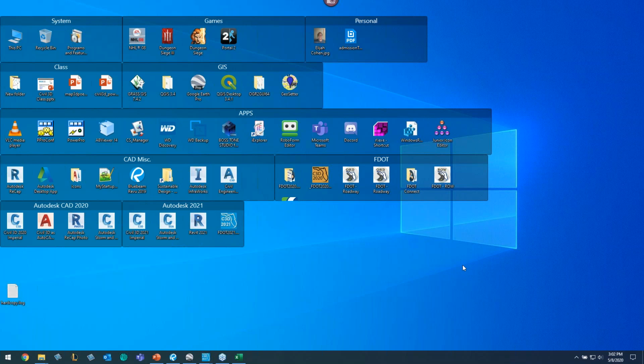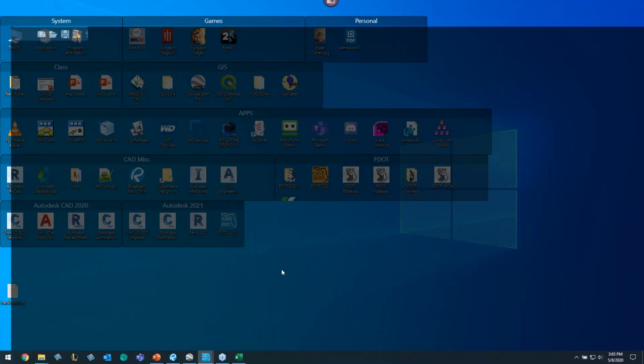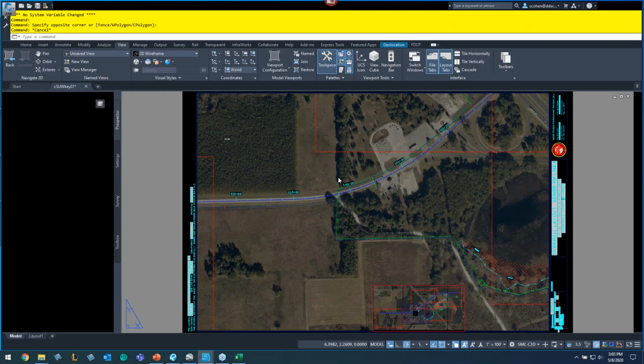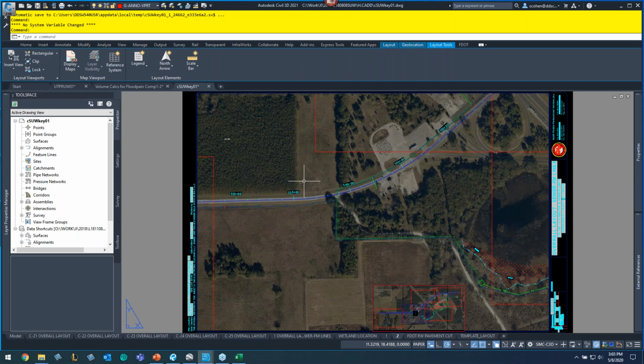I don't know where I want to plot, so I would just bring that rectangle into CAD and then move it around, because I'm defining where I want to plot with the view. But yes, in theory, you should be able to trace a viewport and do CH space. In fact, let's check it, because here's the only problem with that. I know we're going over a little bit and if you have to leave, I apologize, but this won't take too long. I'm thinking it won't work because the viewport is in the same exact spot as paper space. So I don't know if it'll be able to find it, but let's just try.